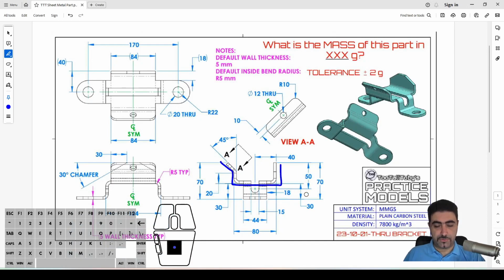It's obviously a contour flange, and we can see that flange to flange on the outside we've got 80 millimeters. The height of this flange from the bottom to the top is 70 minus 30, that is 40 millimeters. And we can see that we've got 20 millimeters to the start of this bend. That means that I will need to make this flange as a separate command because I don't want to be doing the math to calculate how I should change this 70.